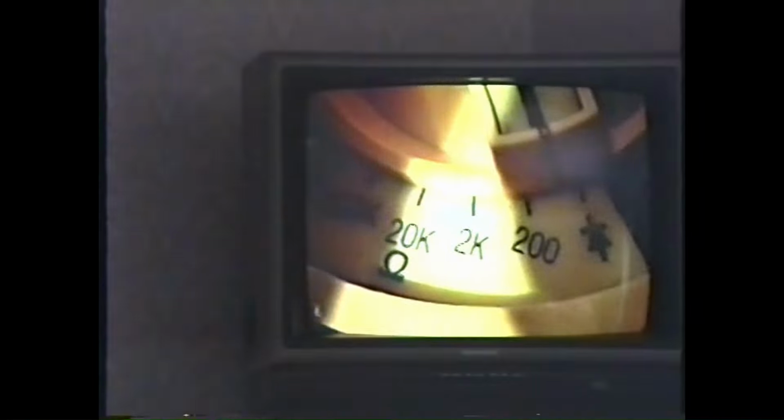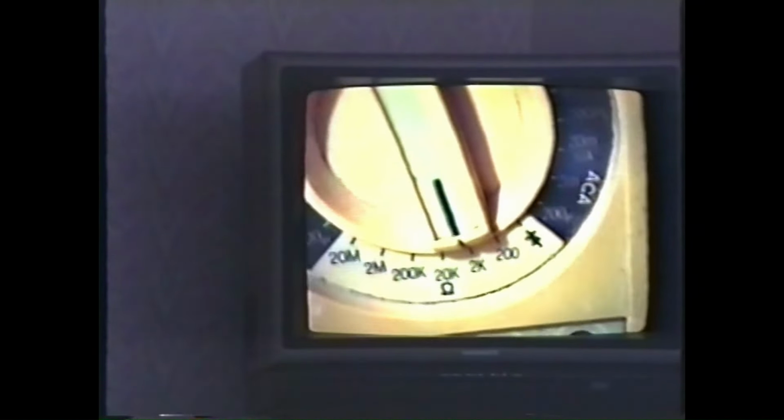If you look at the meter, down here is the ohms department. Right there. For instance, when the meter is set on 200 ohms, we can read up to 200 ohms. With that setting, the meter will read up to 200 ohms, actually 199.9 ohms. If you set the meter on the K scale, you can read up to, in this case, 2,000 ohms. Whatever you read on the meter display up here will be in thousands of ohms. That's very important. If the meter is set on K, and the display says 1, it's actually 1,000.